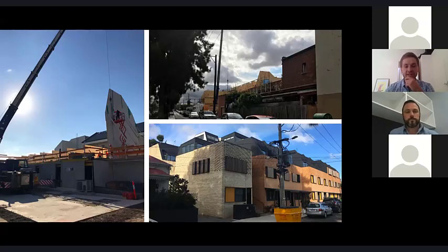Yeah, and we didn't do the concrete on this job, we were brought in late, but this just highlights, even from a traditional or conventional structural approach, that need to look at a project holistically and think about these things early on, and actually think about construction loading. That's something that's generally really separated. It goes to the builder, and then the builder has to engage a temporary works engineer and things like this. But on this project, I believe they had to back-prop the slab quite significantly for this crane and these sorts of things. It might be cost effective in some applications to actually just reinforce these elements to be able to take these construction loads.